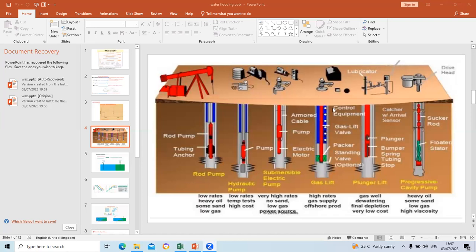So we have a system where the gas is injected inside the annulus. Then we have an operating valve, probably at this level. There are a series of steps that are taken to determine the depth of the operating valve. We cannot go into that. We are going to organize an extra training on the artificial lift method.